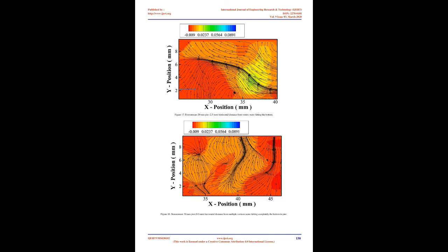In Figure 12, it can be seen the percentage of distance downflow vortex relation from each pier to the upstream area. The blue color represents the 10 mm pier with 27%, red represents the 20 mm pier with 34% and gray represents the 30 mm pier with 39%. Therefore, there is a 12% difference from slender pier to thicker pier due to the obstruction. Figure 12. Percentage about distance downflow vortex relation.